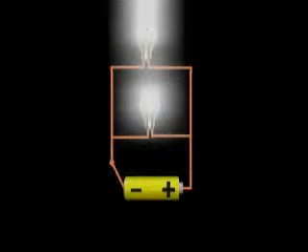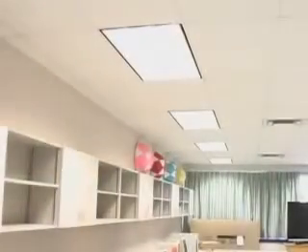If we follow two electrons traveling through this circuit, we see there are two possible paths. One electron leaves the negative terminal of the battery and travels through the upper bulb, the other through the lower bulb. They both end at the positive terminal of the battery. Parallel circuits always provide more than one path for the electricity to travel on. If you are in a room with a row of ceiling lights, these lights will be connected in parallel.